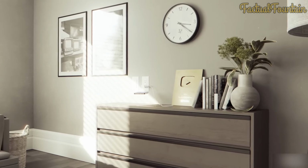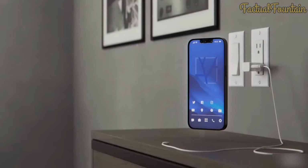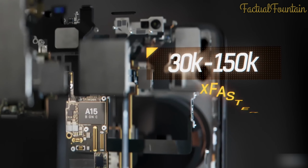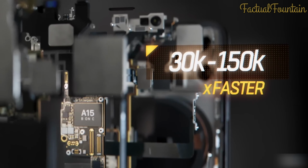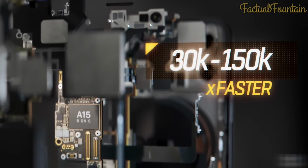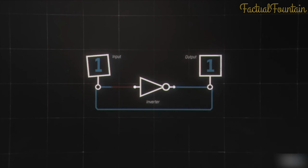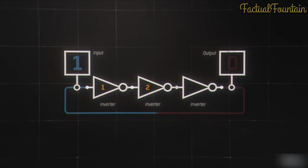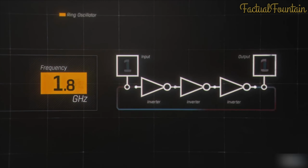Let's move on and see how smartphones and computers generate a clock between 1 to 5 gigahertz, which is 30 to 150,000 times faster than a single oscillation of this quartz crystal tuning fork. Let's look again at this inverter looped back upon itself and add 2 more inverters into the loop, thus creating a ring oscillator. Due to the odd number of inverters, the output rapidly oscillates between a 1 and a 0. These inverters can operate incredibly quickly and can easily reach the gigahertz frequency range and higher.